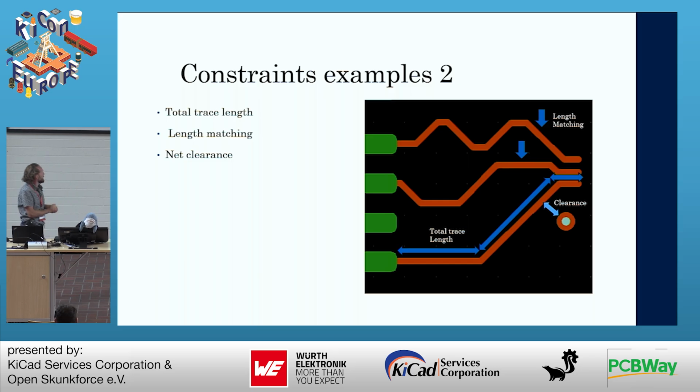where, as in the example here, you have a via and a trace, and what should the clearance between those 2 nets be? You can have a general constraint saying what the clearance between 2 nets can be, but you could also, let's say the via is in one net class and the trace is in another net class. Is there a specific clearance requirement for those 2 nets? Let's say there's noise in one of the signals and you don't want that noise to contribute to anything in the other signal. Well, then you might want to add clearance between those signals to avoid that.